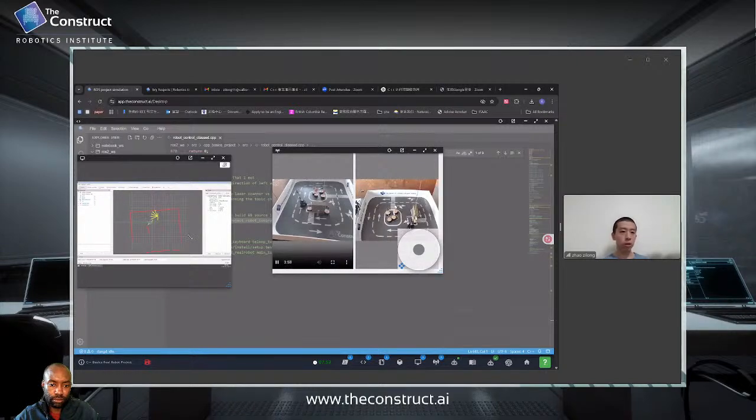So this is how it runs. When it gets close to a blocker, I think at 0.3 meters, it will do a turn, and the left turn and the right turn is based on the distance. Like if the right turn is 0.5 meters and the left is 1 meter, it will turn left. If there is no blocking in front of it, it will move straight. And if it detects something on its left, it will turn a little bit right.